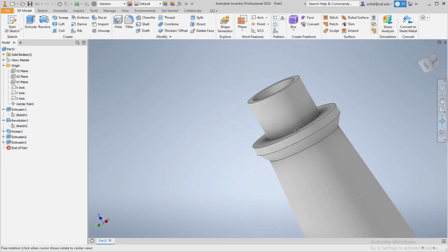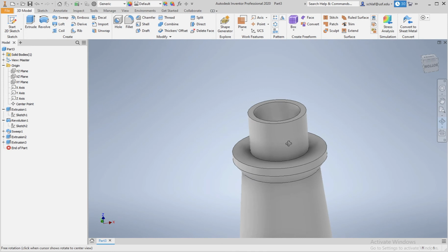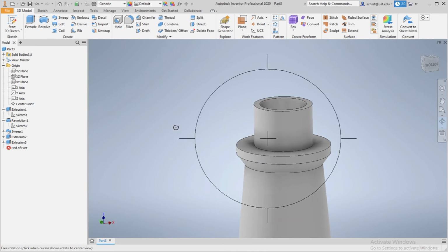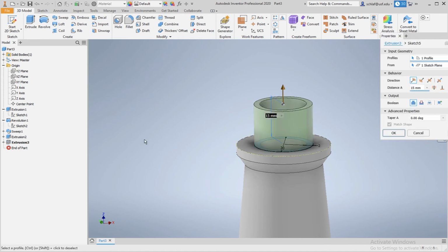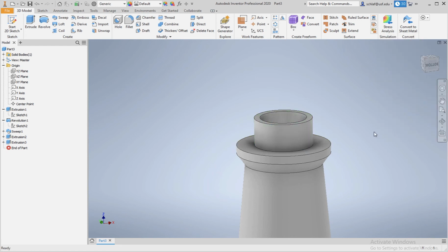And okay, so this is maybe a little bit too high. So let's change this. So I double clicked on extrusion number 3 here, and I'm just putting in 10. And here. Okay, so this is now the base for our housing for the actual light.